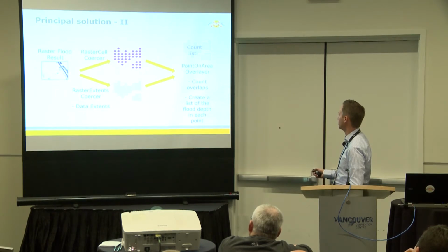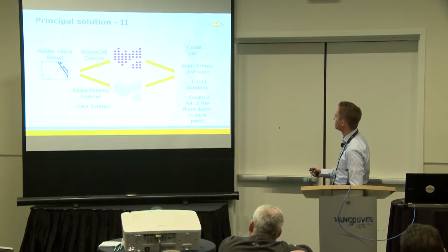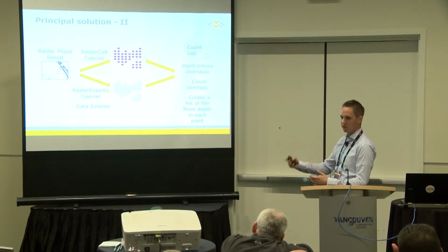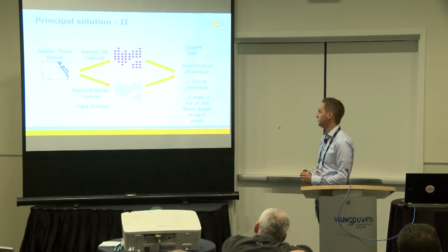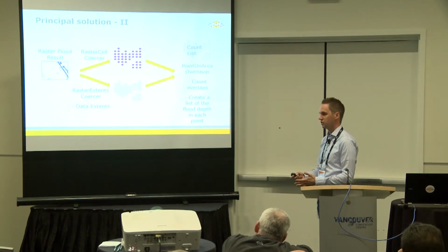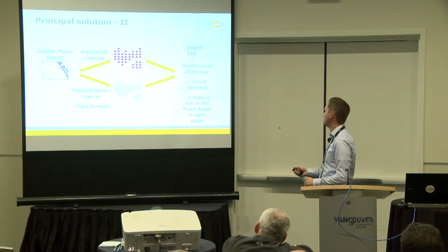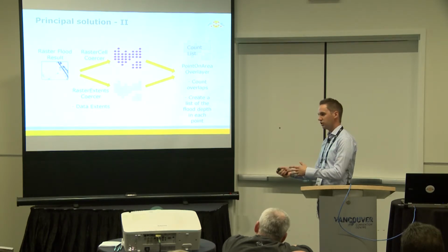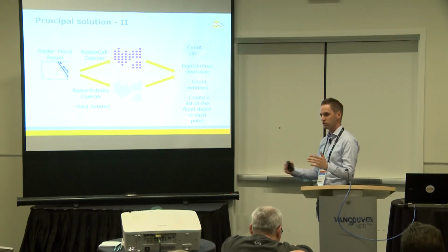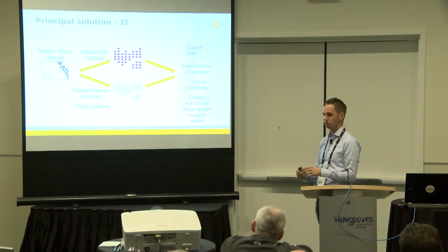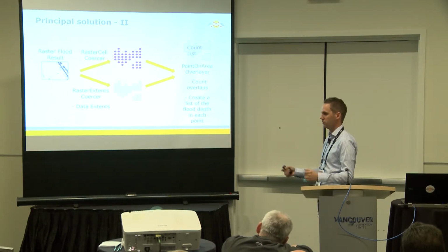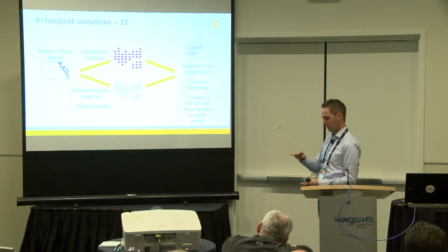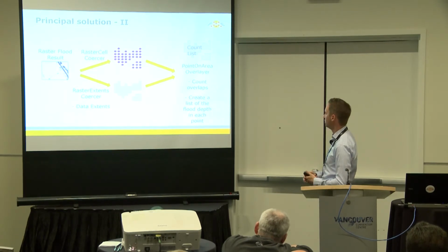And then I use a point on area overlayer, and that one gives me a count of how many hits it had, how many cells were inside this polygon. And by knowing the size of each individual cell, you can just multiply that area and then you get the total area. And you do the same with the volume. You calculate the volume for one and then summarize them.